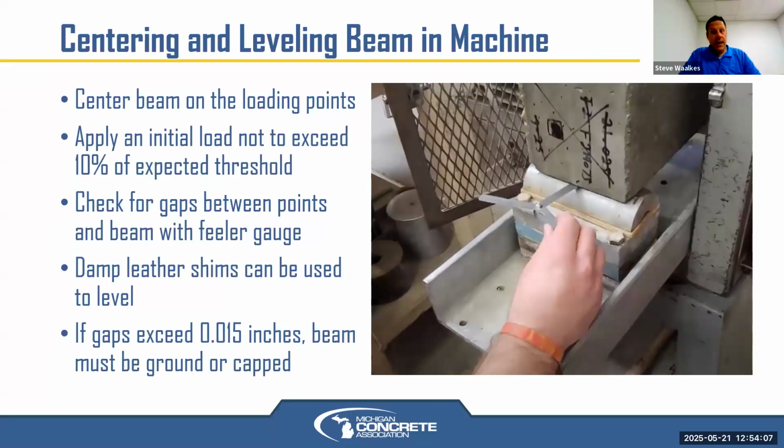Beams are done a lot in the field for opening to traffic. You do not require a certification to do it. It's pretty much information only. Whether you can open to traffic or not, there's no payment typically based on it, unless it's a concrete patch job, in which case, if it meets opening to traffic strength, then it meets the required strength for the joint repair job or longitudinal or transverse full depth repairs.